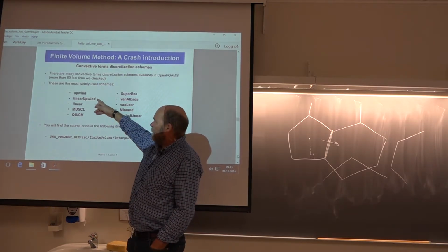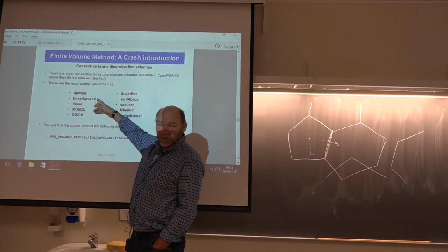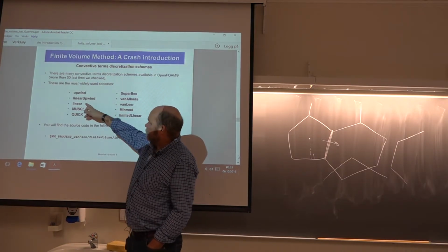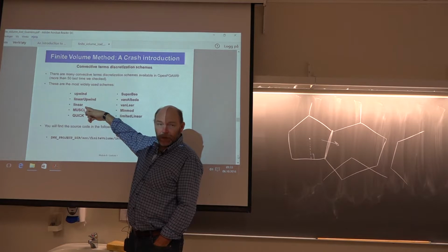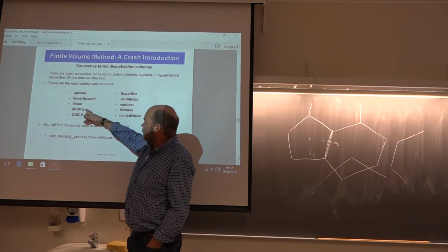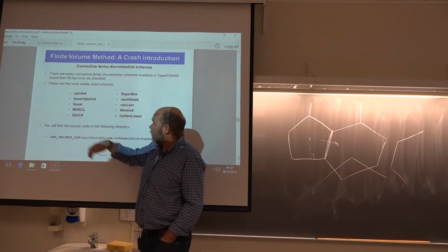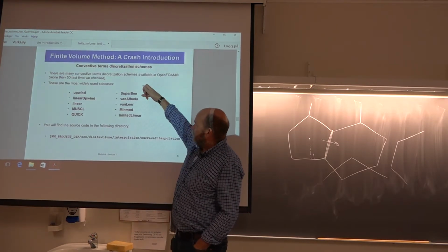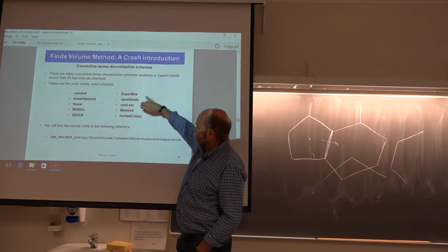Linear upwind, that's the second order accurate. That's not so stupid. Pure linear, be careful with that one. It can explode. That's the central scheme. Muscle, more advanced. Quick, more advanced. Super B, very good. And so on.